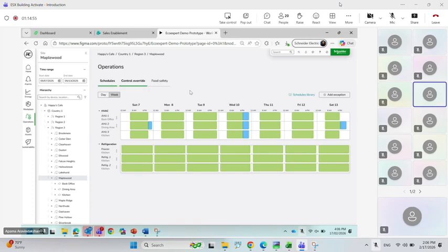We can create a logic in the alarm threshold saying that these two conditions have been happening, that is, power consumed high and temperature not getting achieved, which is an indication that your compressor might be faulty or about to fail. Or the AC is running at 50% capacity because it's a 12 kilowatt unit, hardly consuming 6 kilowatt for the last 1 week.